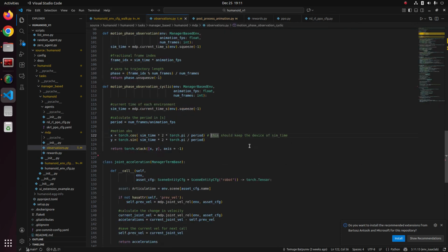The first thing that's changed from the last video is I've switched to using motion phase sampled from a unit circle, which was described in the Disney robot paper, and I think also in DeepMimic. In the previous video I used a seesaw shape, so when the phase goes to 1, it suddenly drops to 0. By sampling from a circle, we have a smoothly looping phase signal.